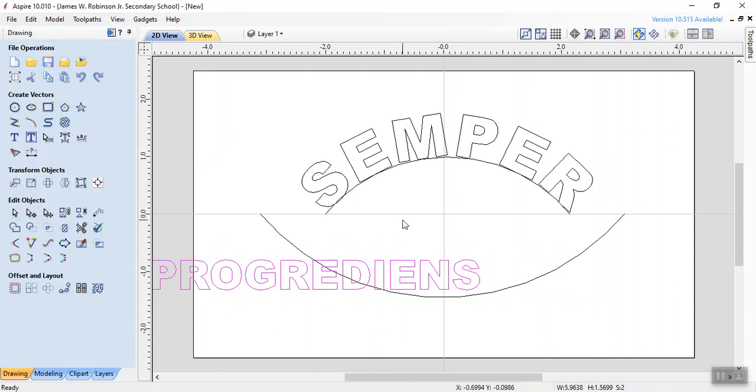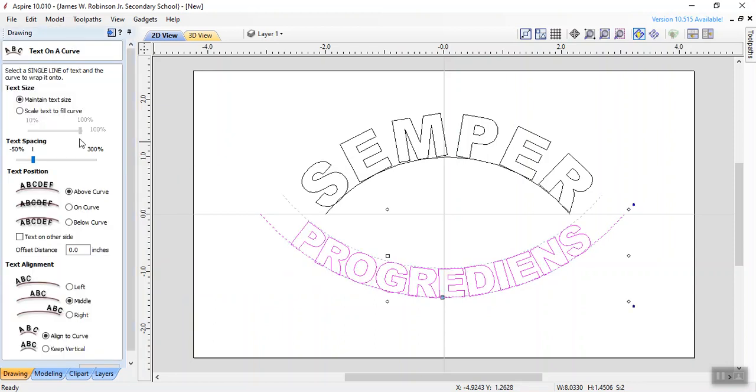And close. Now select the text, press the Shift button, select the arc, and select the text at the same time. Then move your cursor over "text around the arc" and click on it. As soon as you do that, the text wraps around above the arc.